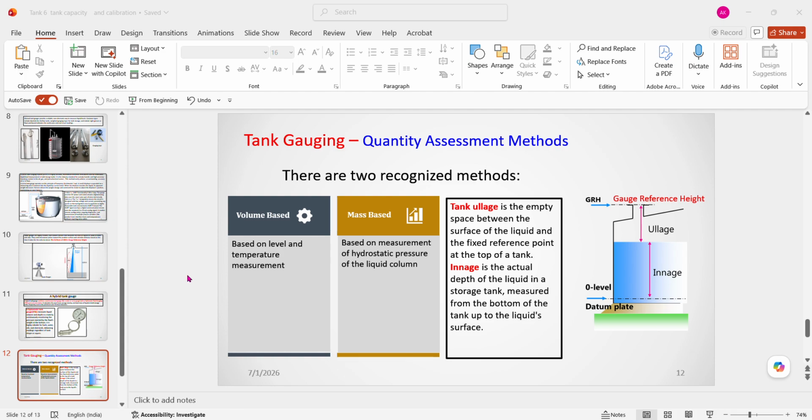And then magnetostrictive probes. Magnetostrictive probes are commonly used at gas stations. A float rides along a vertical rod to track where the product is, and the water level, precisely using a magnetic pulse. So these are the processes; different fluids require different processes. You have to adopt different processes for different fluids to get the actual level of the fluid inside the tank.